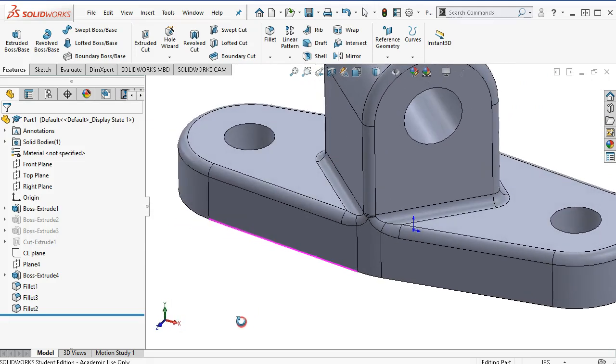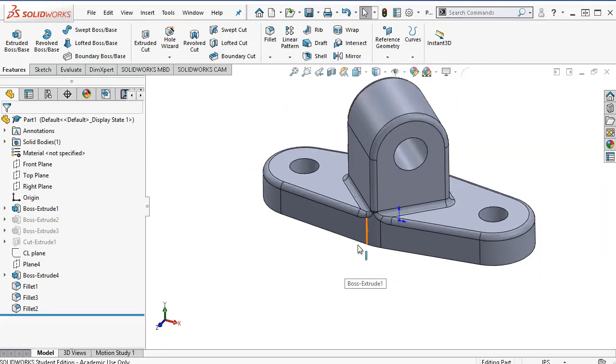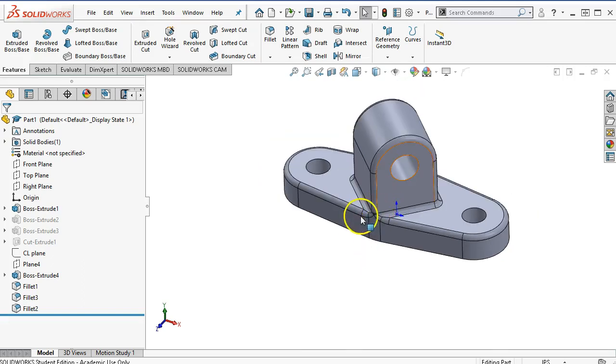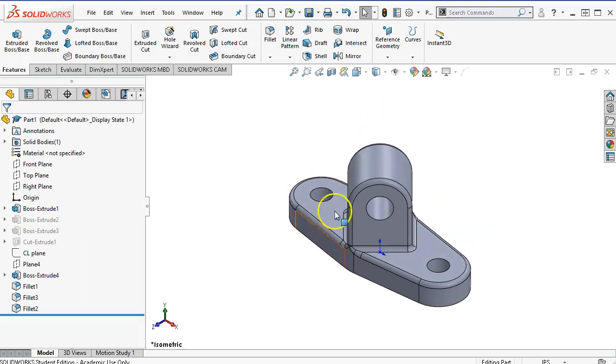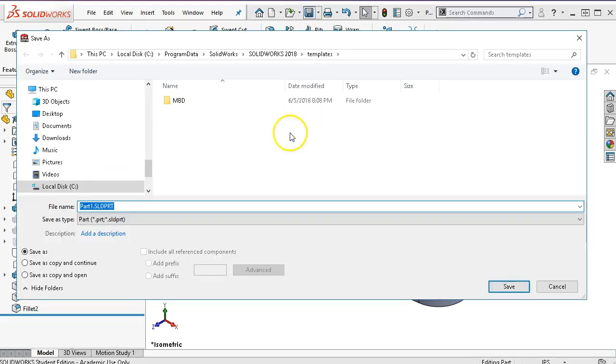I want to say from a machining standpoint, with the complexity of those fillets, that's going to be a file to suit. I'm really not going to run a 3-axis program that deep over that geometry. So we'd come around the outside, blend those surfaces as much as possible, take a round file, and clean up the corners. All right, so that is my exercise 8.13.